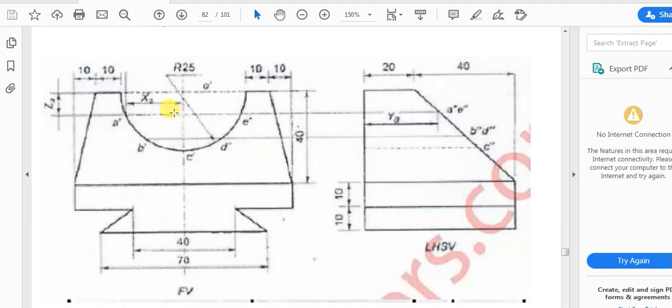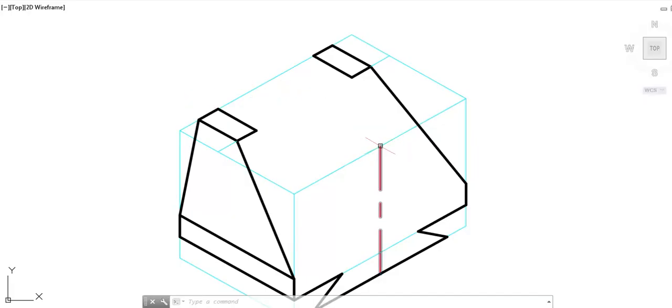After that let us proceed to the method to draw this kind of circles on an inclined plane. Let's call them isocircles. Now they have already divided this into a number of points. Of course we will be dividing in the same manner. One thing is important here: the radius of the circle and the center point of the circle. We can see the center point of the circle is the topmost middle point of this front view. So let us proceed in the same manner. This is the probable center point of the circle, which is located in the middle of the front view.